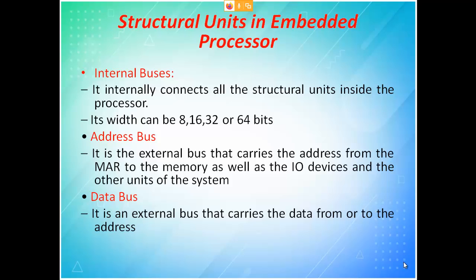address. Now you put 2 to the power 2. What combinations are available? 00, 01, 10, 11, which is nothing but 4. 2 to the power 2 is 4. So the total number of lines in memory I can address is 4 lines. This is not sufficient for us.